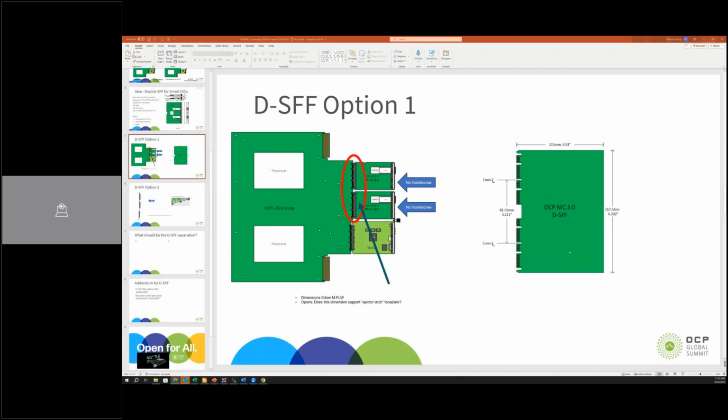cooling an 800 gigabit capable NIC. Now, the second thing is that once you go to an 800 gigabit NIC, Gen 6 servers from the host side are not available at this moment and will not be available for quite a while. When we roll out 800 gigabit, we do see the need to break out 32 lanes of PCIe Gen 5.